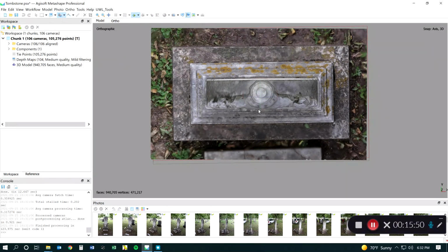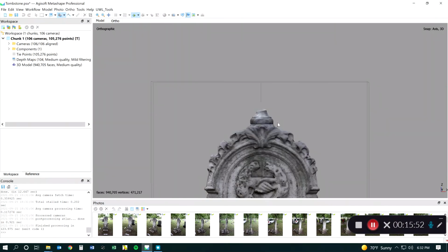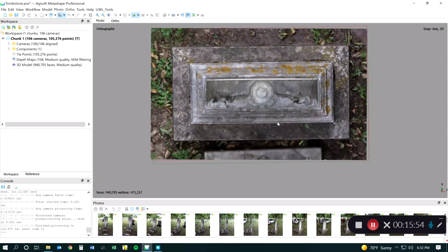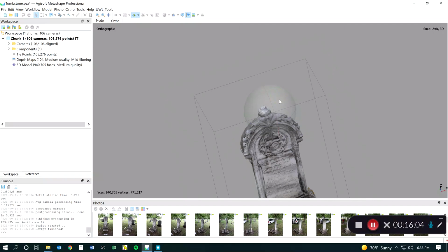And then once I have it where I'm pretty happy with being back in alignment, now I can go ahead and just click bounding box of coordinate system again, and now make sure that I click on my navigate icon before I rotate my model.